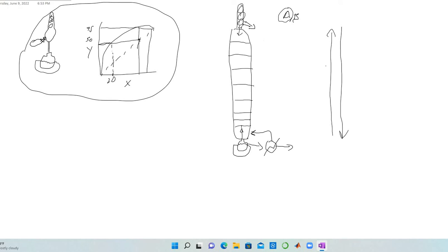What's going to happen as the liquid and the vapor pass each other between trays is there's going to be this thermal stripping effect. So the vapor, as it passes the liquid, is going to essentially vaporize the more volatile component using energy of condensation of the lesser volatile component. And vice versa, as the liquid's going down, it's going to condense the less volatile component and use that energy to vaporize the more volatile component in its stream. I think I just repeated myself, but it's kind of an important idea to understand.